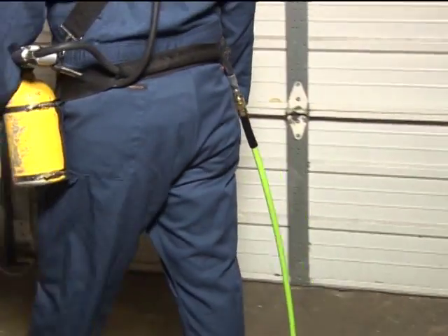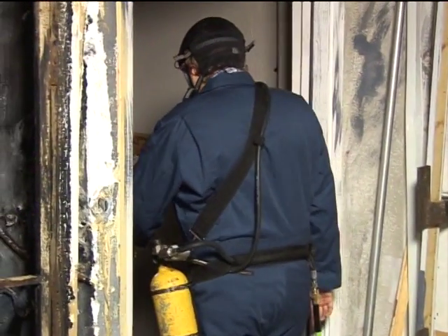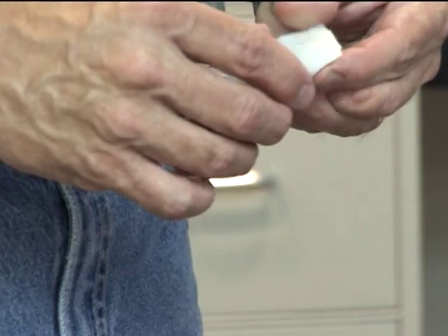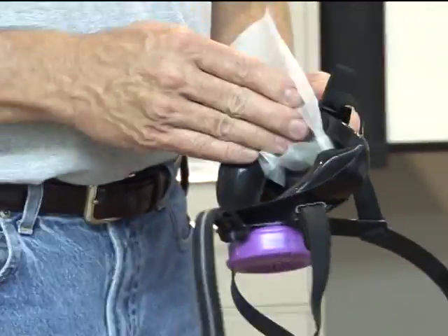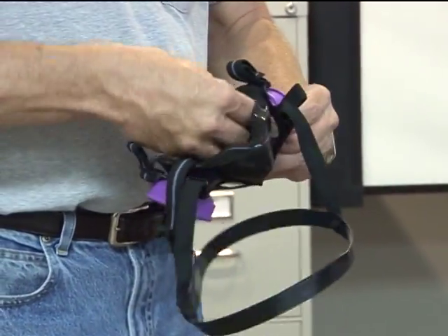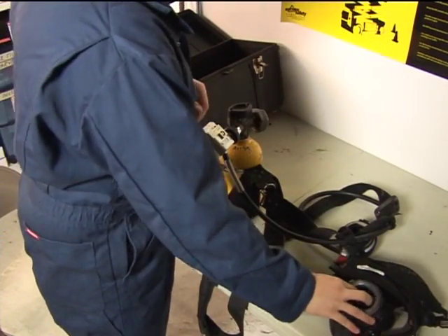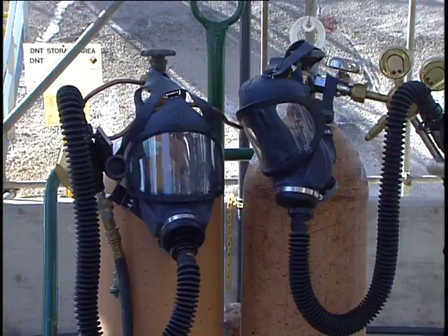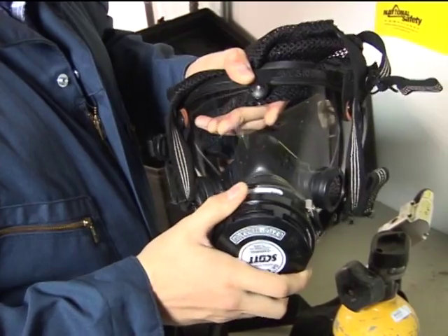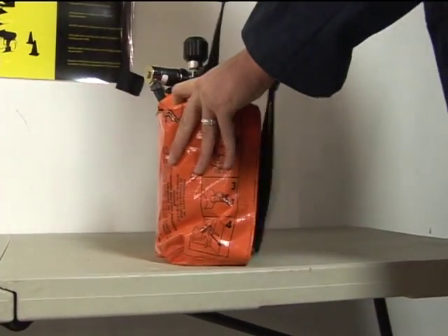The proper functioning of respirators and ensuring the devices themselves do not pose a hazard to the user require an ongoing and regular maintenance and cleaning schedule. In general, respirators should be inspected for basic function prior to each use and cleaned as often as necessary to prevent the occurrence of unsanitary conditions. Inspect respirators used routinely before each use and during cleaning. Respirators maintained for emergency use should be inspected monthly and according to manufacturer's recommendations. Emergency escape-only respirators should be inspected before being carried into the workplace for use.